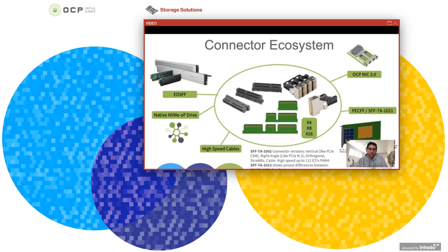And really the most important thing is, we see PCIe Gen 5 going to 32 gigatransfers per second, up from 16 gigatransfers per second in PCIe Gen 4. So you really need better signal integrity on the SSD to basically reduce platform cost on the overhead for PCIe Gen 5. So that's where we see EDSFF getting really exciting.